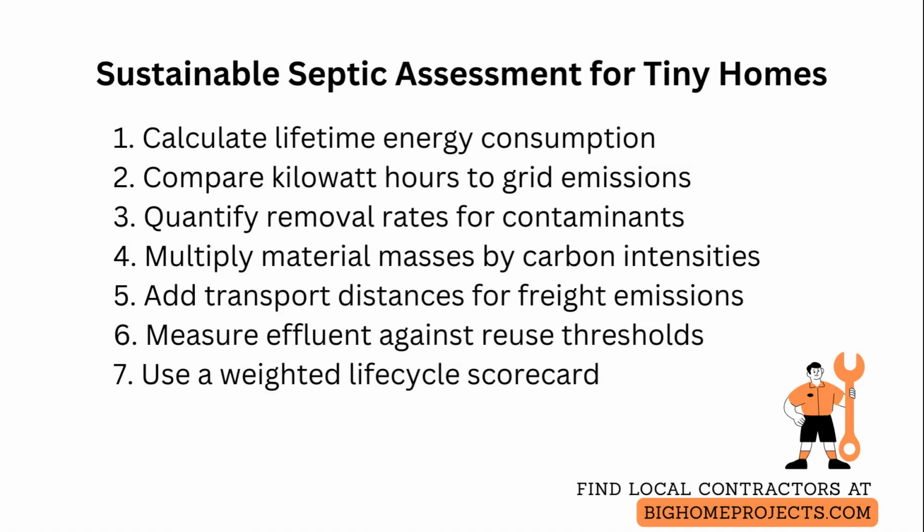For passive systems like sand filters, constructed wetlands, and composting toilets, quantify performance by looking at removal rates for total nitrogen and biochemical oxygen demand and match that to the sensitivity of nearby surface or groundwater receptors.